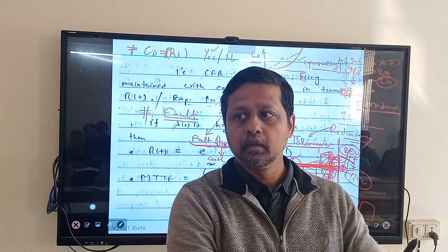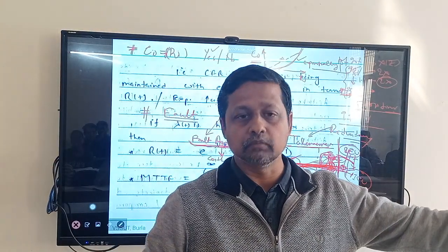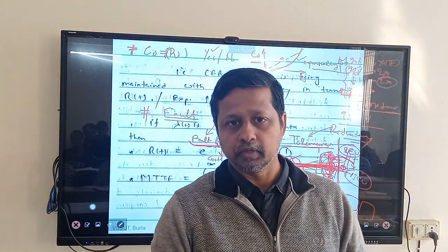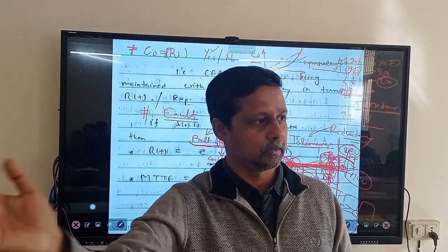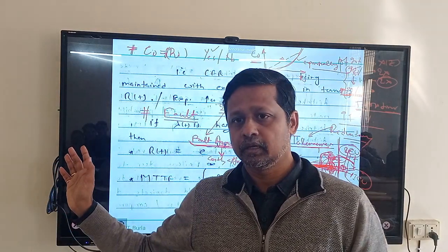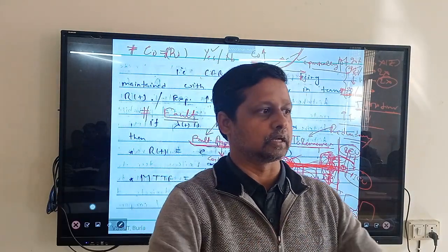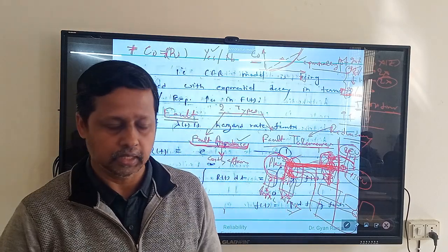If all the gates face the same problem, then what will happen? The dam will be out of work. So whenever they construct, you see in the design that they always provide a bypass line. They will simply divert the flow of water through that bypass line without generating power. Understand?